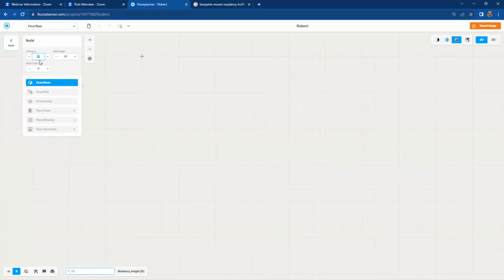I'm going for 5-inch thick walls here in the US: 3.5-inch stud walls, metal or wood, and then 5/8 inch gypsum board on either side, making about a 5-inch thick wall. 10-foot high ceilings. Always remember that your ceiling heights are very important. They're creating your flat ceiling automatically.